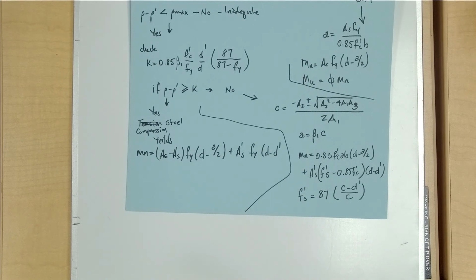So if I have 120 kip feet, I have 1,440 kip inches. But you can answer that question yourself if you check the units, right? This is area, square inches multiplied by kips per square inch gives me kips. Multiplied by a distance in inches, it's kip inches.